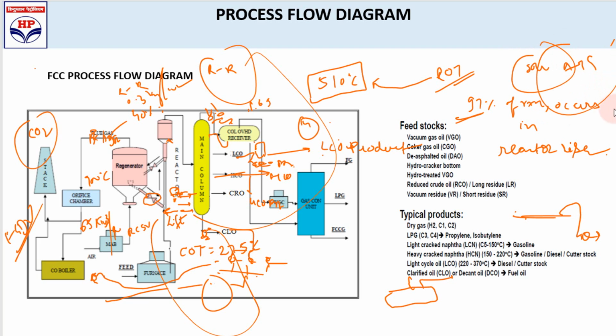The gas from the sponge absorber is sour ATG. The sour ATG goes to the SRU, gets treated, and becomes sweet ATG. Sweet ATG comes back to the gas plant. The purpose of the gas plant is to provide fuel gas to all the units that have heaters for burning. This fuel gas is the ATG we generate after treating, and we burn it.